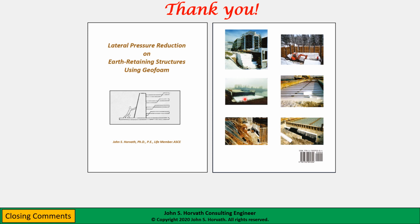So they were using EPS block geofoam to minimize the weight of the embankment on the underlying subgrade, as well as to reduce lateral pressures on the abutments that you see here.